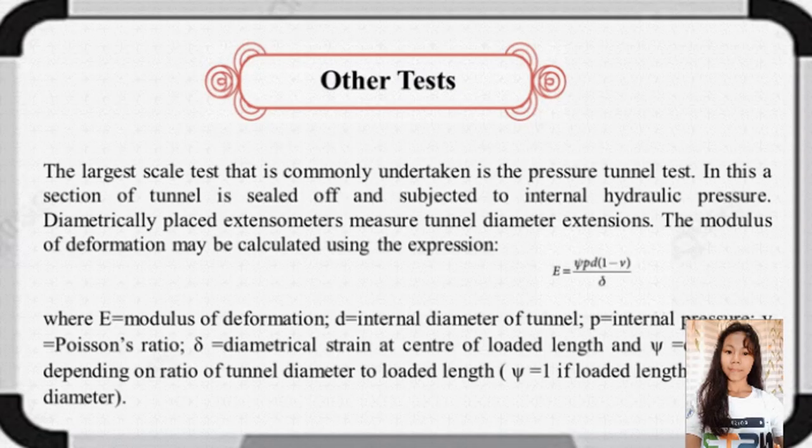Other tests. The largest scale test that is commonly undertaken is the pressure tunnel test. In this, a section of tunnel is sealed off and subjected to internal hydraulic pressure. Diametrically placed extensometers measure tunnel diameter extensions.